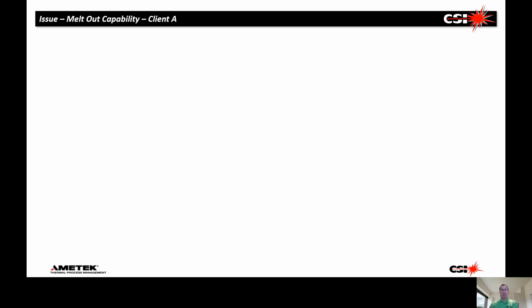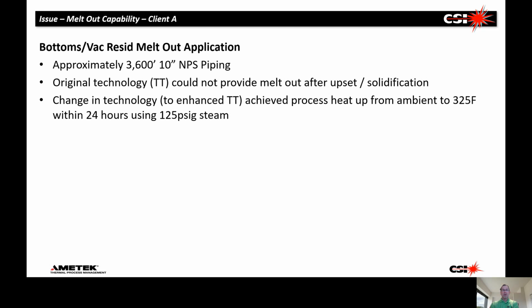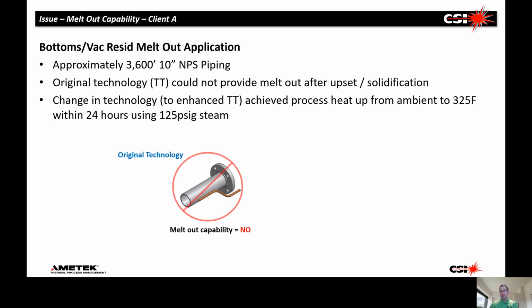So when we look at a couple of examples of different clients that have gone through these issues, this is a bottoms or a vac resid meltout application where we had large bore piping, tube tracing originally on the line. The tube tracing, as demonstrated in the presentation, could not melt out after the upset. So this particular client wanted to change the technology to something that could melt out within a 24-hour time period. And so the original technology of tube tracing did not work. The revised technology, in this case an enhanced tracing, could achieve that melt out within that time frame,